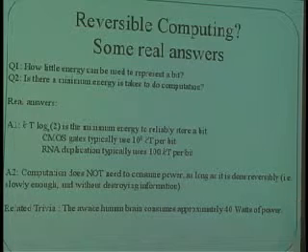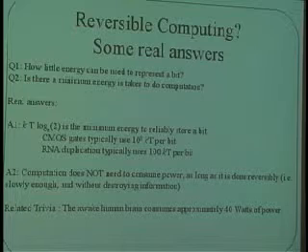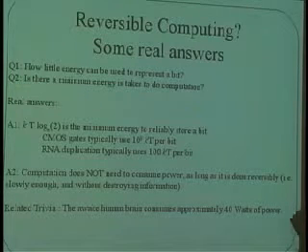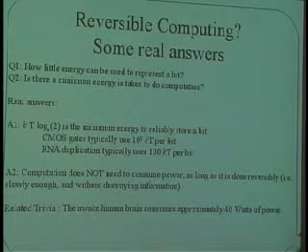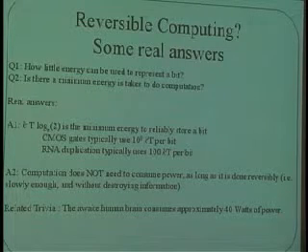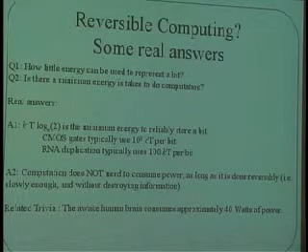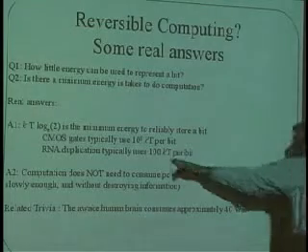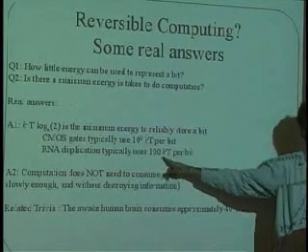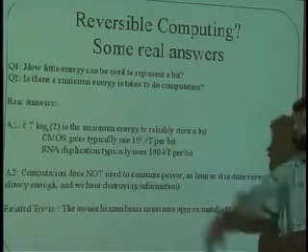So we have many, many years to go before we get down to the fundamental limit. Of course, as we scale down the size of the parts, the capacitance that we use goes down. As we scale the voltage down, the 1/2 CV squared goes down as well. So the energy is going down, but we're still at 10 to the 8th. What's amazing is that to duplicate a single bit of RNA uses 100 kT. So even there is 100 times more, but it's a heck of a lot less than 10 to the 8th. So nature has us beat by a long shot.